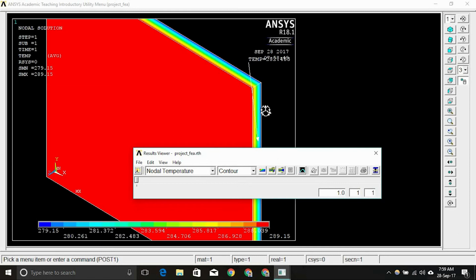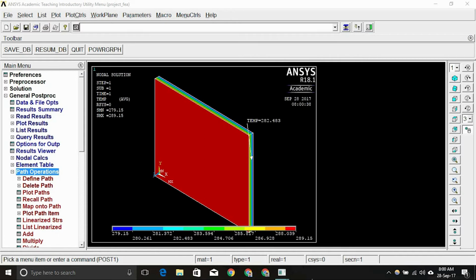The location is not good, but it is displayed there. Once we close the window, we can see that the annotation that we set in the result viewer is still there. So if you are making a PDF or something like that for a presentation, we can use this as a tool to display a value at a particular position.